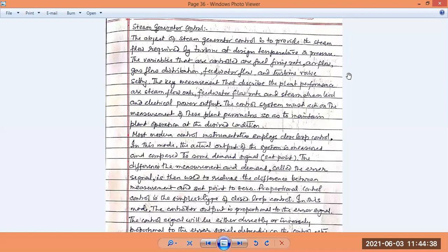So based on which factor, maximum, what is this? Maximum important is the steam turbine setting, mostly the steam turbine setting, that controls the plant steam flow rate, the steam extraction rate and the electrical power output. The variable factor that controls the steam rate is the turbine valve setting.